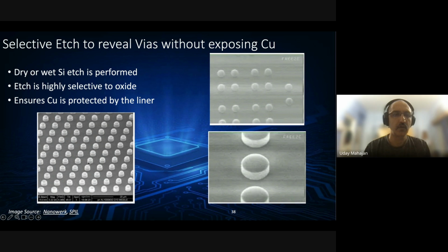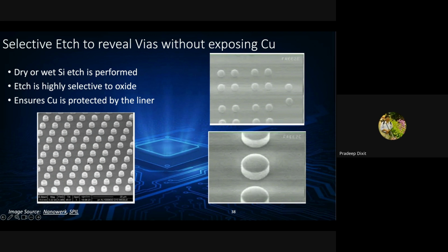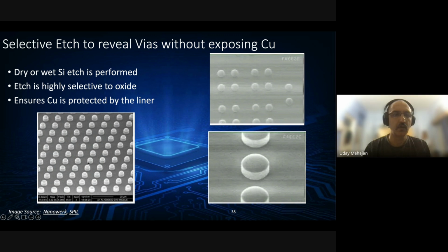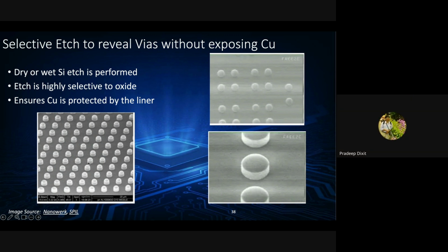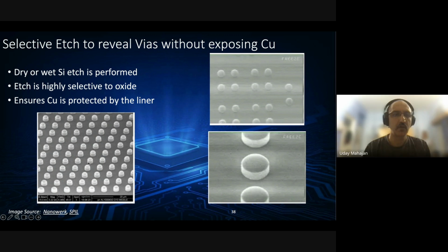firstly, I think your assumption is the wafer is 700 microns thick, right? At this stage, it is more like 50 to 100 microns thick. You thin down the silicon, so your net amount of silicon to be removed is a lot less than 700 microns. And uniformities, I do not remember, to be honest, because the information I have is also now a few years old.